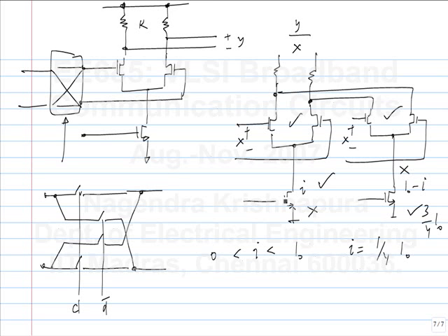Yeah. No, this is a single tap, but the tap value maybe goes from, let's say, -half to +half, right, in some steps. It can't go in a single step, because that means the value of mu is very large. You can't implement that while being stable. So, let's say you want variation between -half to +half in steps of 0.05. In that case, each of these current sources will have to be a combination of parallel devices.